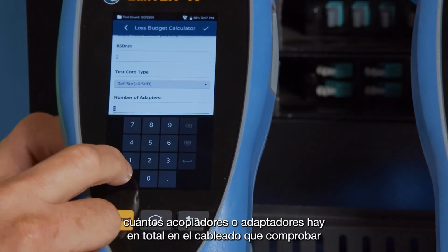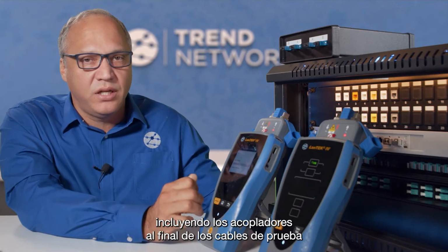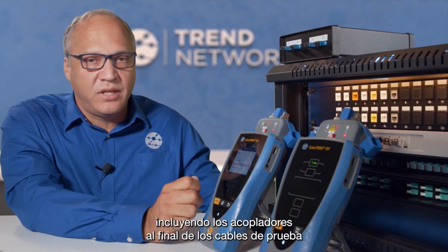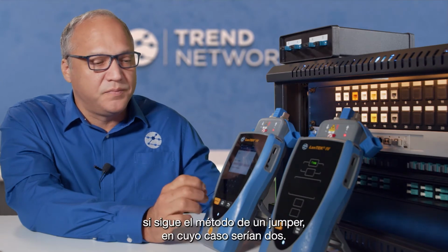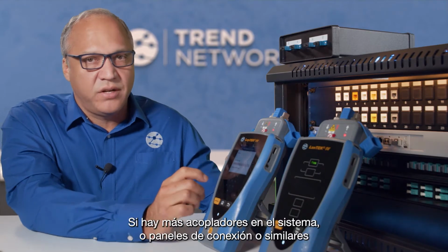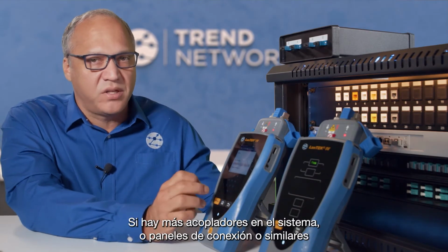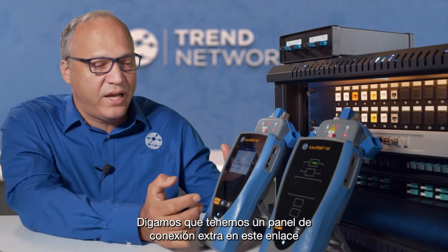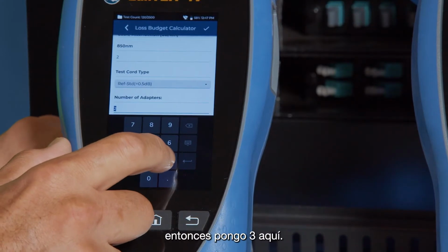How many couplers or adapters in total are in the cabling you're going to test, including the couplers at the end of your test cords if you're doing the one jumper test method? Then that would be 2. And if there are any additional couplers in the system, or patch panels or something like that, you would need to add them. So let's say we had 1 additional patch panel in this link. So we'll just change that to 3.